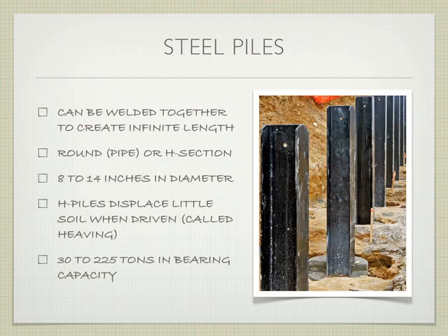Now, what would be some of the disadvantages of steel? Cost, sure. Corrosion. So if we were to say, guess what, we need to retrofit Venice, we're going to use steel piles, what would we be concerned with? Corrosion, salt water, those kinds of issues. So that's a big problem.